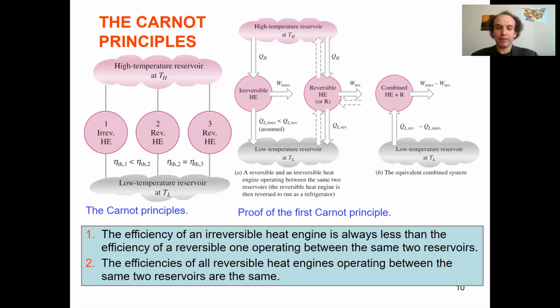Right? Okay. So how to do second law analysis here? How to check if you have a reversible, irreversible, possible or impossible cycle? Find one ideal cycle operating at the same reservoirs, at the same conditions. Find one cycle, only one, it's enough. And then you will know that all other cycles will be not better. All other cycles will have the same efficiency if they're ideal, and they will have less efficiency if they're not ideal. Do you understand?